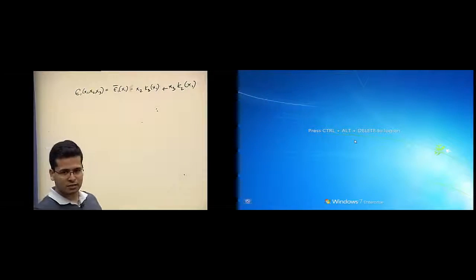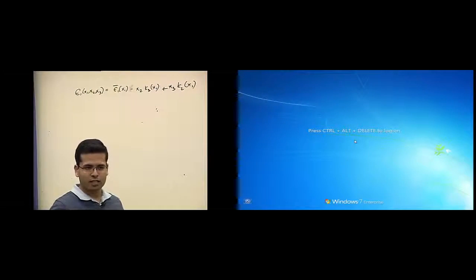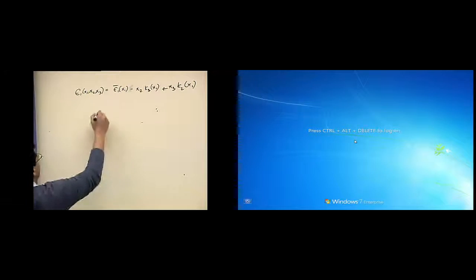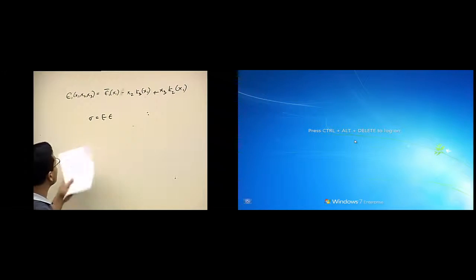So now, to evaluate stresses, we have a very important law. Can anyone tell me? Hooke's law. So it is based on some assumptions. What are the assumptions? Linear elastic. Isotropic. Yes. Homogeneous. That's important. So Hooke's law, we apply that here.